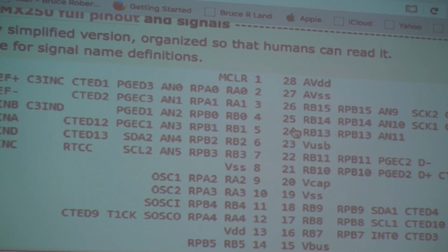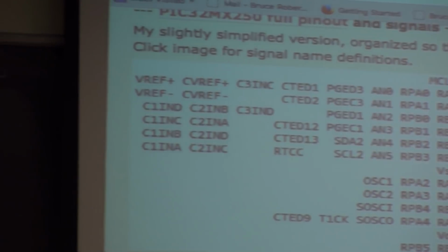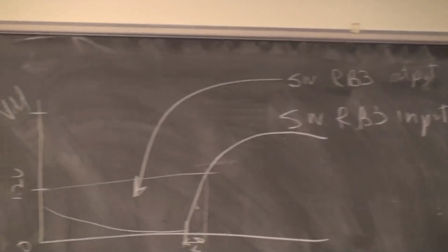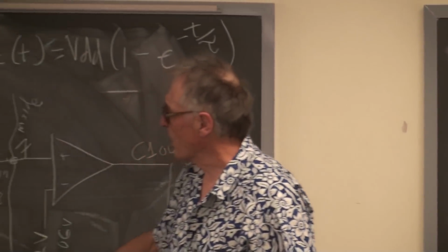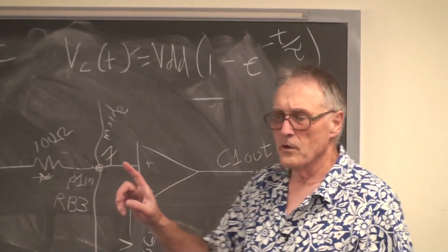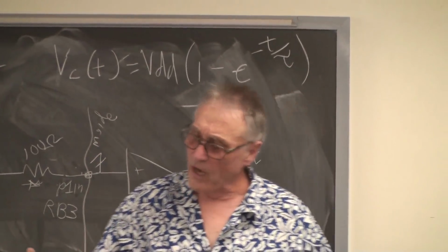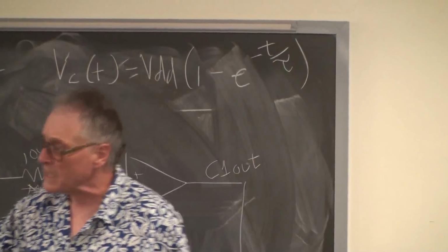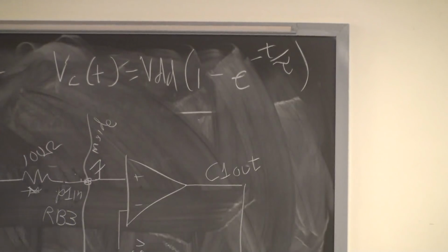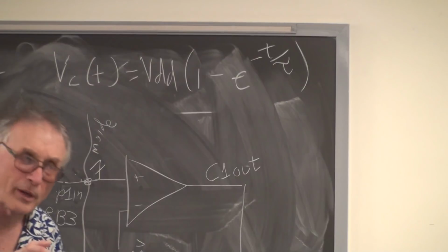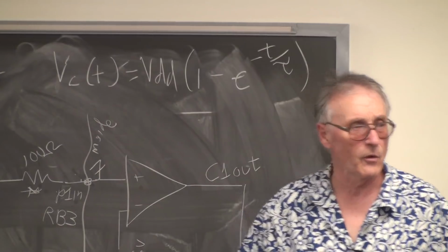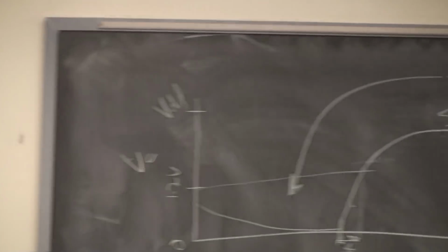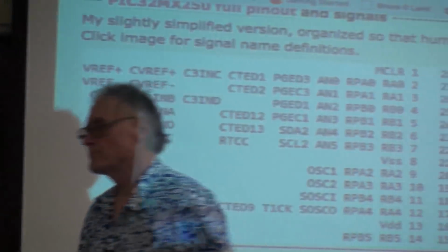Pin 24. That's not even a typo, it's a braino. So, pin 24. So you have to go through these 2 steps of identifying the name of the signal on the peripheral pin select, get the group number, map it to an I/O pin, and then that's mapped to a physical pin, which in this case is pin 24. So RPB13 maps to pin 24.